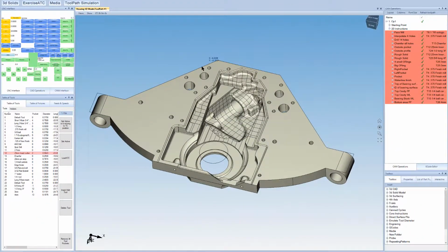Okay, so as I was saying, we pre-drilled all of these holes as a first operation. Then we've gone through and cut all this outside stuff, which is some pretty heavy machining. Now we're going to tell the machine to move to this location right here, and then this location, or actually we can pick any of the locations, but these two would be good. And then we're going to check them.